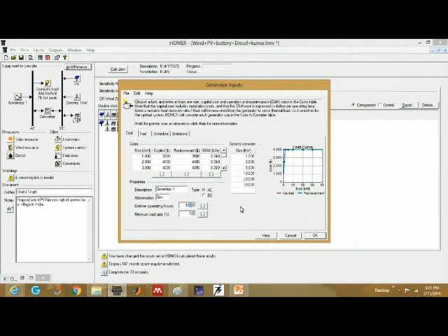So if you run it for the full year, that's a generator, within 2 years you need a replacement, because in a year 8,760 is the number of hours. In 2 years it exceeds 15,000 hours. So one constraint is that you want to keep the running hours minimum, so that the life of the generator becomes longer. See?